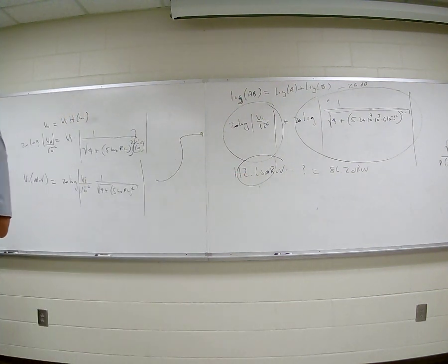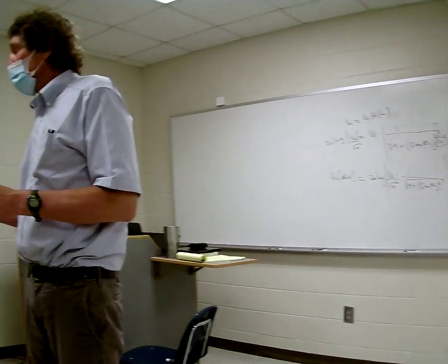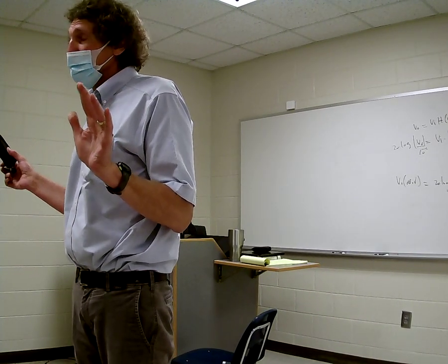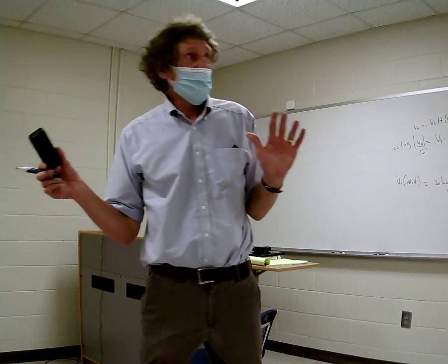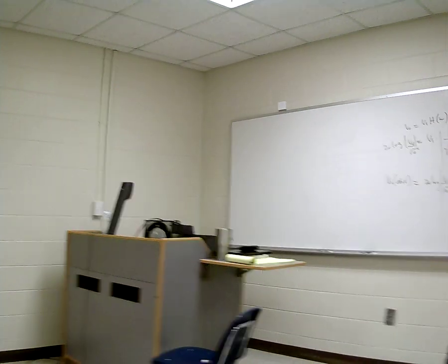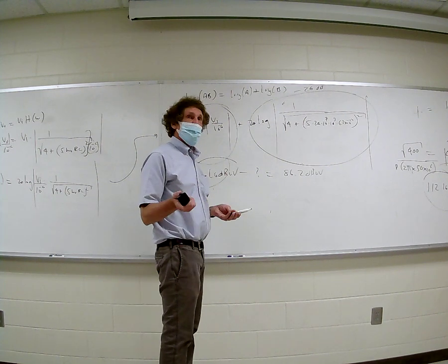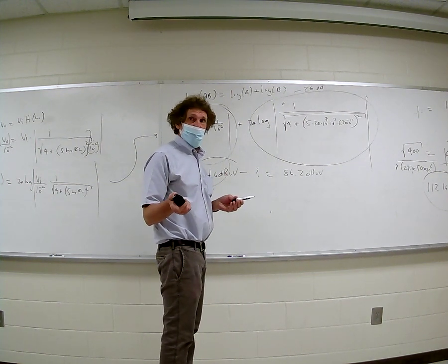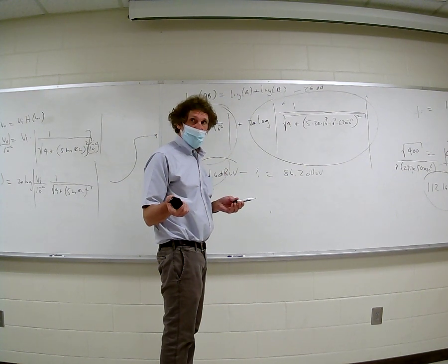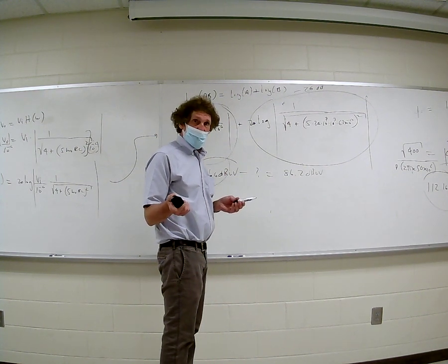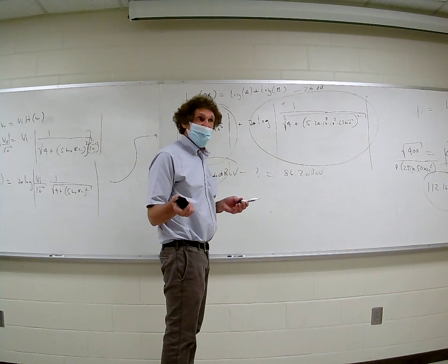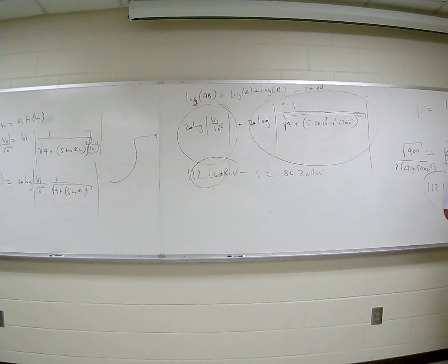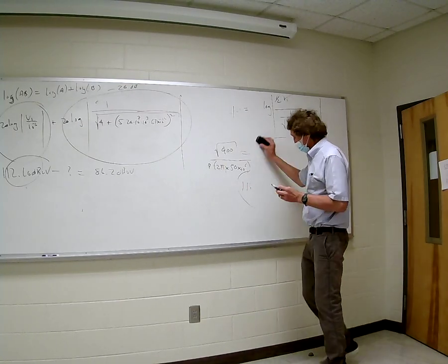It depends on the circuits, but generally if you get 60 dB of attenuation, pretty much it's dead, for most things. 60 dB is a huge amount. And you're already down that far. If you just think about it, 10 dB is a factor of 10. 20 a factor of 100, right? 30 a factor of 1,000. What's 60? Factor of 1,000,000. 60 dB is a huge amount of reduction in signal.